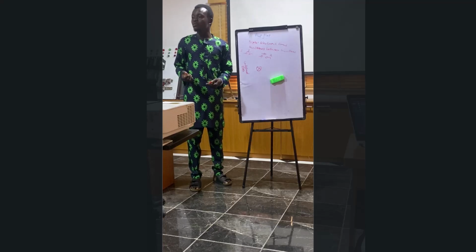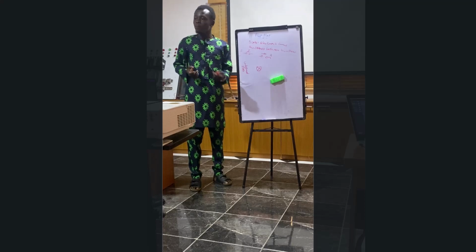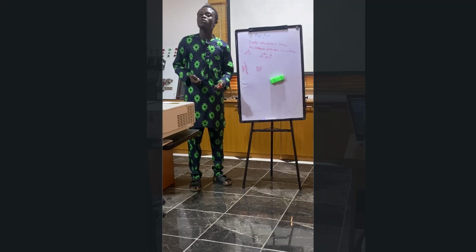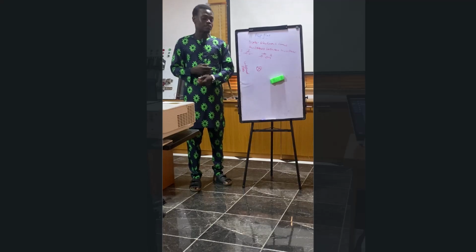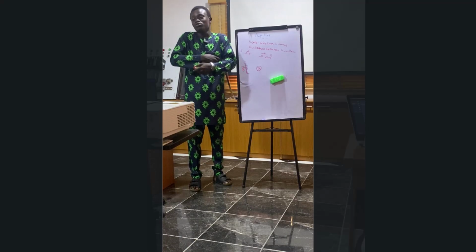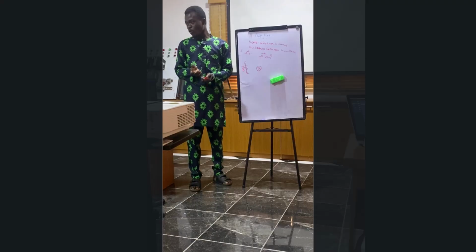And if you press the reset button, the lamp should remain off until you press the set button again. So when you are not pressing any of the buttons, the last state is what is going to be retained. And in a situation where you press the two, it is supposed to have an undefined state. You don't know whether it's going to be on or off.